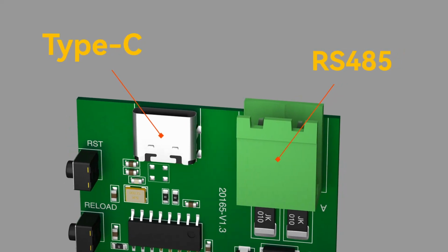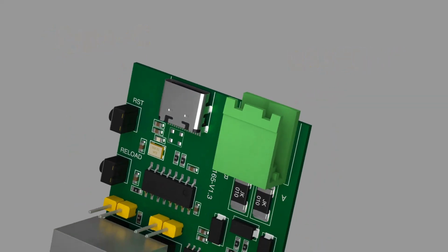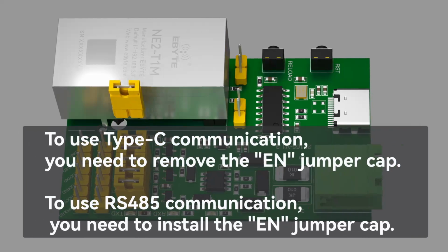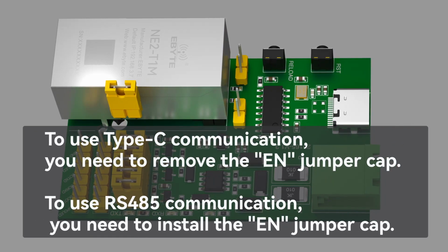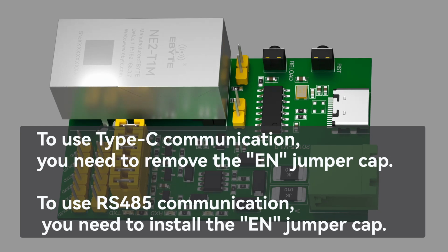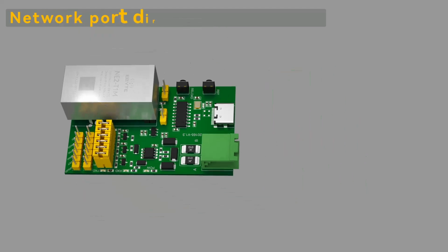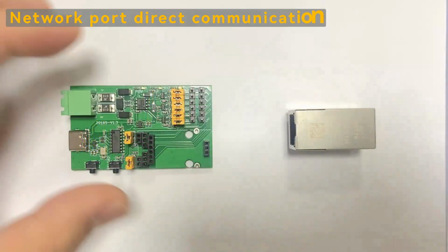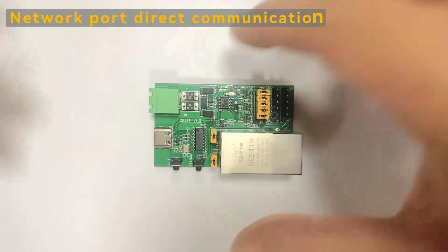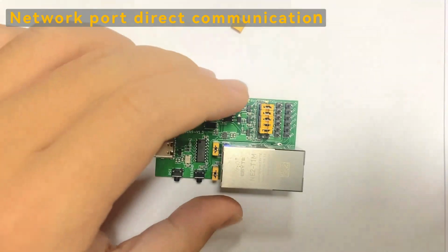The test baseboard is equipped with a Type-C interface and an RS485 interface. If you choose to use the Type-C interface for communication, please remove the EN jumper cap. If using RS485 communication, the jumper cap needs to be installed. Using the Type-C interface is relatively simple. Just plug the module into the board and connect it to the computer via a Type-C data cable.